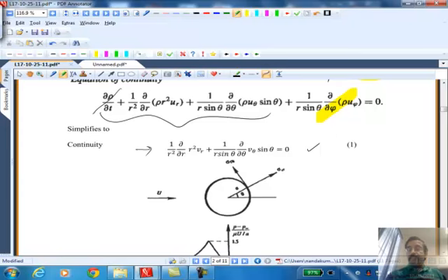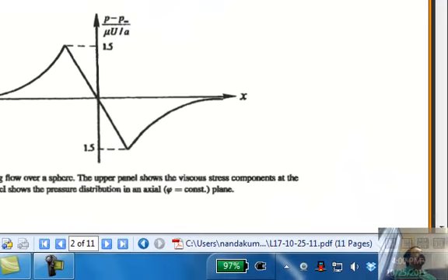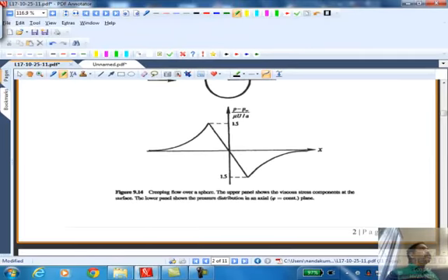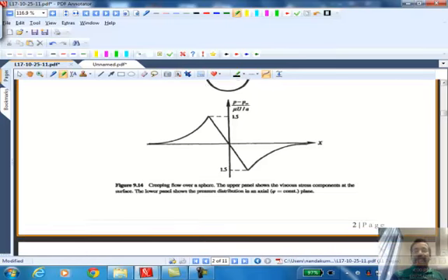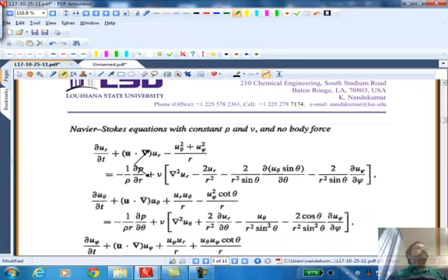Now, how do we do that? As I said in the last lecture, either you can take the definition for stream function in Cartesian frame, do a coordinate transformation, which we did at the very beginning of the class, or you can look at the book by Happel and Brenner. It's an excellent source for all the material on low-Reynolds number hydrodynamics. At the end of this appendix, he has curvilinear coordinates and he has the stream function expansions in each one of those various coordinates. Cylindrical, spherical, ellipsoidal, spheroidal. There are many, many such coordinates that he deals with. And we are just going to take the definition, and in an exam, I'll give you the definition for stream functions in any non-standard coordinate system.